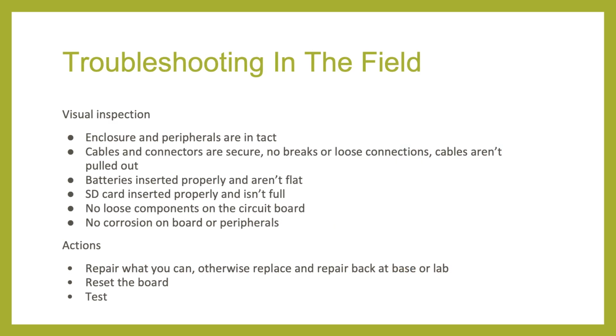So once we're in the field checking on the devices, we usually carry a laptop, and we'll go through in a bit how we debug in the field. However, if you can't carry a laptop, we recommend simply swapping out anything that looks damaged and not taking any chances. So the first thing we'll do is a visual inspection of the mechanicals. For example, is the enclosure breached? Is the gasket in properly? We'll also do the same for any peripherals. Has anything been chewed or broken?